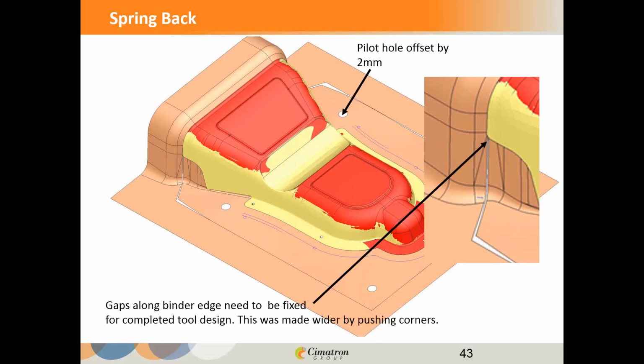It affects the total deformation springback, which tells me maybe when I do offset a pilot, perhaps I'm going to pick one that's further away from the part that has less of an effect, or put it in an offset location where I know it's not going to cause a problem to the deformation. Something to think about, as we look at the detail level that we're getting into working with this. So we pushed that corner back a little bit further. We stayed 80 thousandths steel safe, or 80% steel safe.